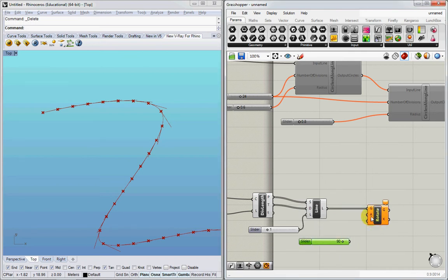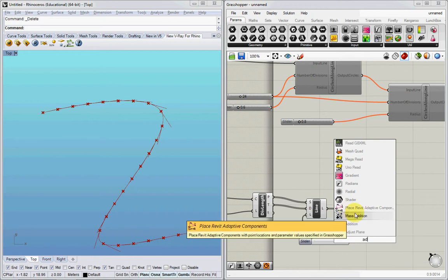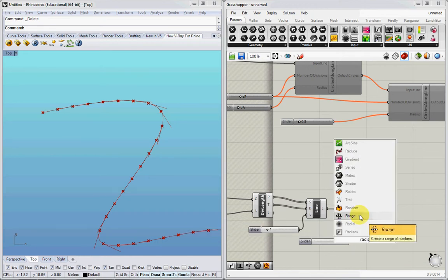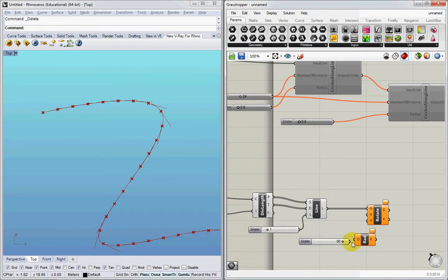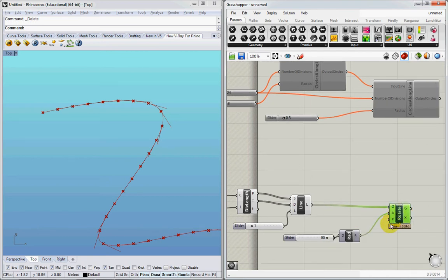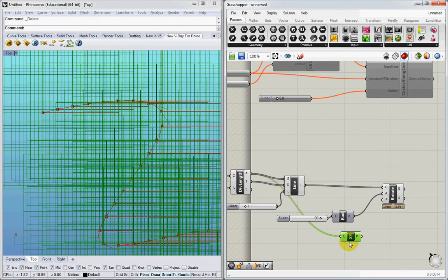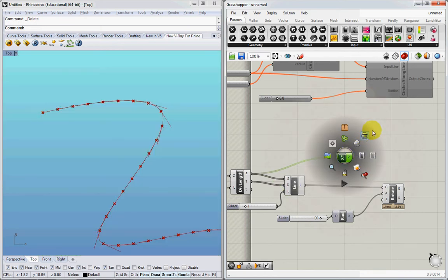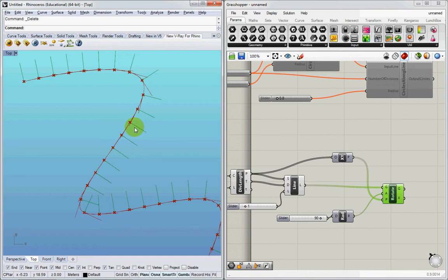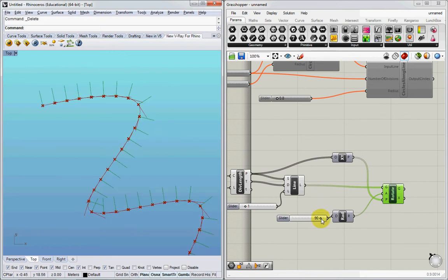But remember, this wants it in radians, so I convert it from degrees to radians. And the rotation plane, the XY plane, but specifically we want the origin to be around each point. That's very difficult, so I'm going to hide that and type that into this. And see, now I've got all these lines rotated 90 degrees. Now if I change that, these guys are going to fall.